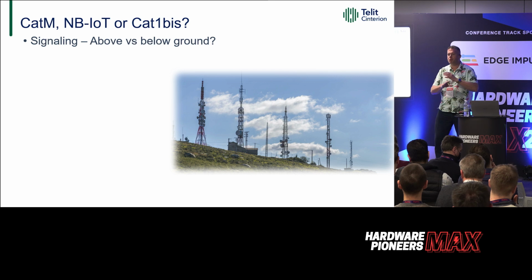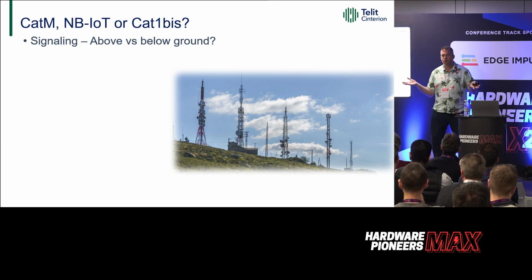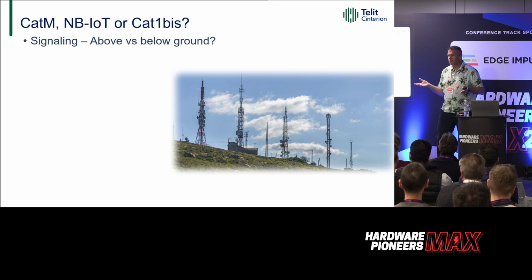which make me choose a different protocol altogether for how my device should work, because I can't do TCP, MQTT over narrowband IoT, because I can't guarantee it's going to work all the time. Cat-1bis removes a lot of those barriers. It kind of makes it a bit more consumer-oriented again when it comes to SIM card choice.